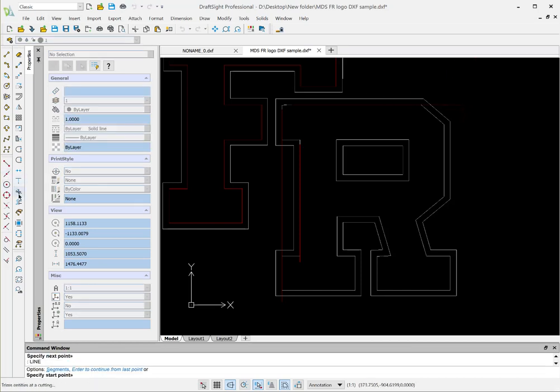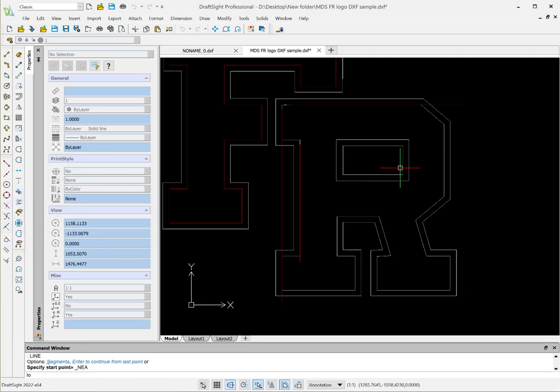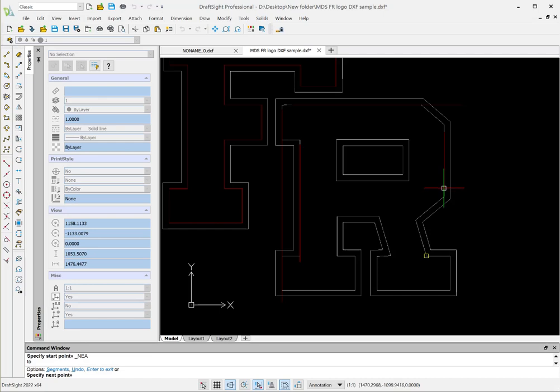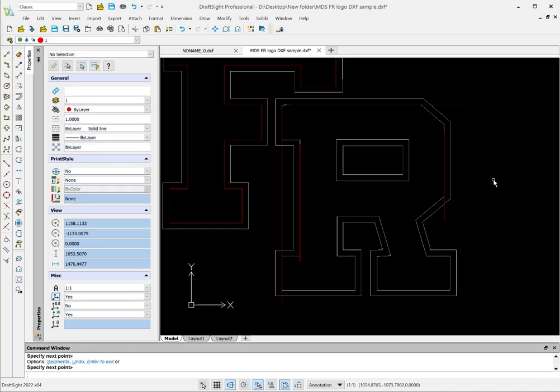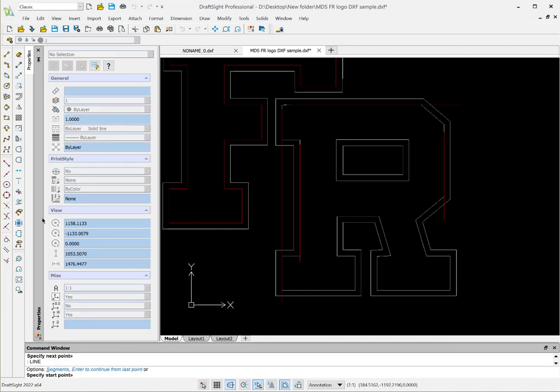line. Now remember, I can only make straight lines right now because ortho's on, so I'm just going to do the vertical lines. Oops, that didn't work out so good. So let's type U for undo. And what happened is I got too close to that snap point, so that's where it went. I need to be over here so there's no little golden symbols, yellow symbols. Okay. Line, near.